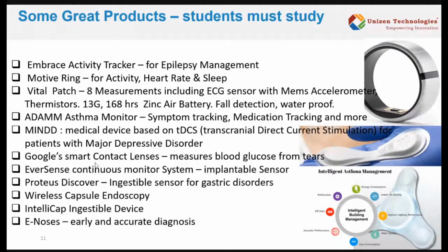You cover it and then put a small gel pad, a thermal pad, underneath this TMP116 so that the TMP116 touches the body properly when the band is put on. So these sorts of complexities are involved in the final design, where how nicely the thermal sensor attaches to your body is the first concern. The second one is that other IC chips which are sharp-edged or something like that should not touch the body and hurt it.